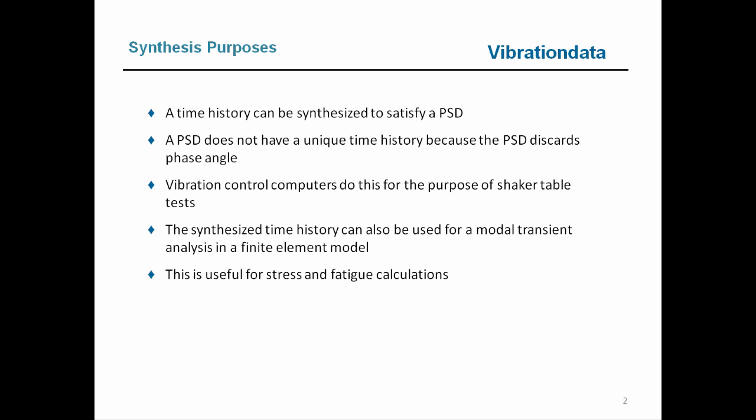Now, another reason we might want to synthesize a time history to satisfy a PSD is we might have a finite element model and we may want to do a modal transient analysis. And that can be useful for stress and fatigue calculations, for example. So sometimes when we do vibration analysis, we like to do it in the frequency domain. Other times we like to do it in the time domain. And the results should come out the same regardless, but it's good to have that flexibility so that we can choose either or both.